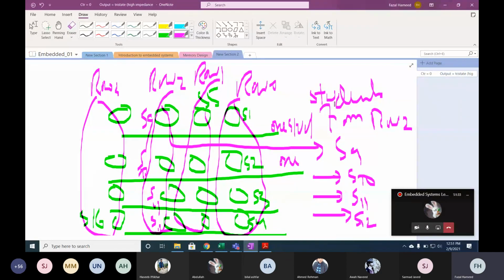4-bit. It's the size of the bus, 4 bits in it. Now we have a bus, and this bus is shared across multiple rows. In this particular example, we have 4 rows. Only one row can be enabled at a time, and there can be multiple bits. Now this bus can also be used for a read operation or for a write operation. Now is this a read operation or a write operation? It's a read operation.